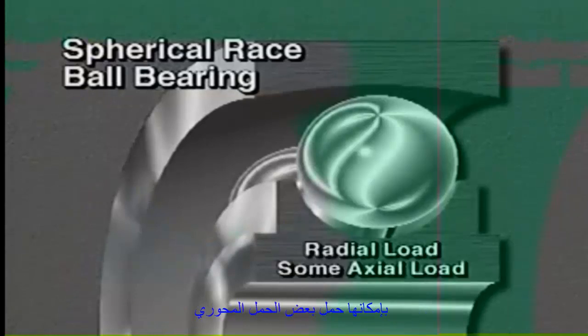This is a spherical race ball bearing. It has a deep groove in its inner ring, but the surface of its outer ring is shaped like part of a sphere. This type of bearing is designed primarily for radial loads, but it can carry some axial load. Spherical race ball bearings are called self-aligning bearings because they can adjust to some misalignment.